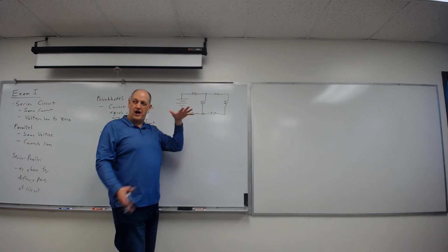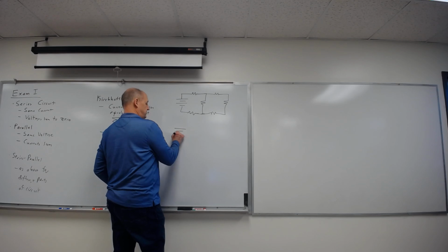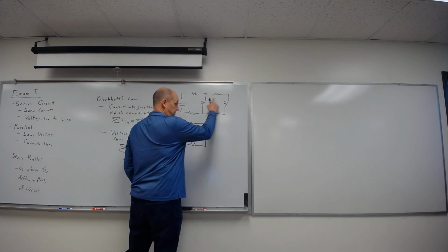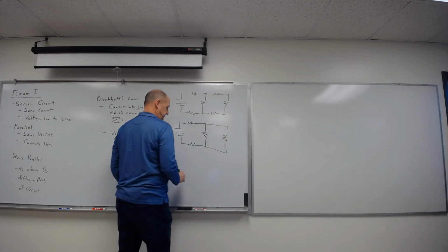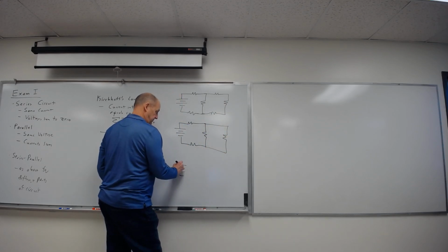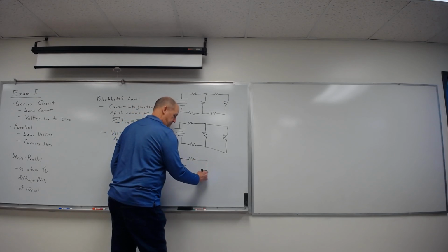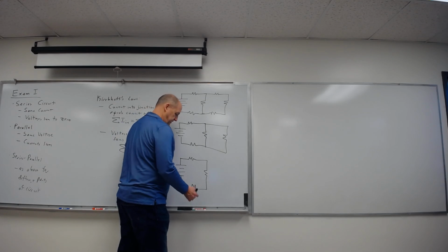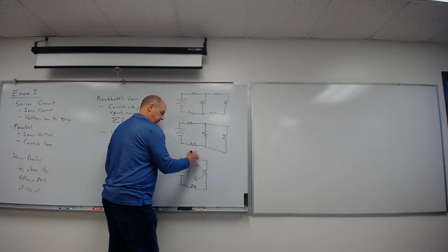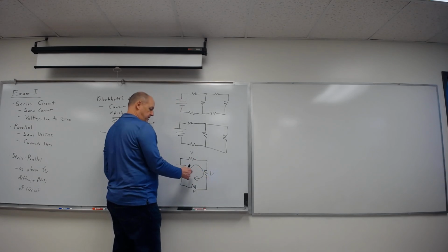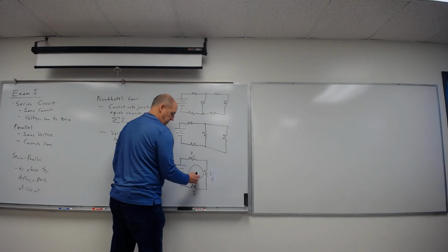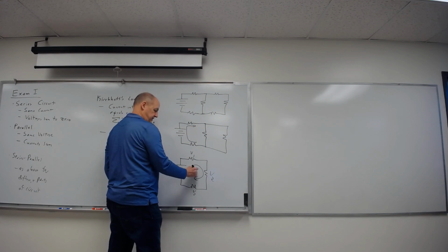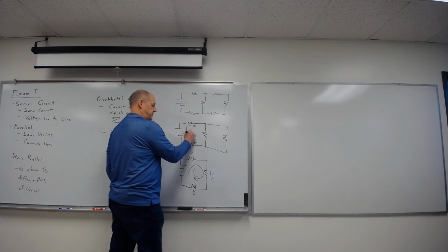And I can go where I'd write all of them out, so I would come through and each step I would write them out. So combine those 3. Combine these 2. I'm left with a series circuit which I can solve. Find that current. Find these voltages. If I go up here, I'll call this V1, 2, and 3. Go up here. This current through this resistor, through here and through here, that's the same current as I found there. Let's call that I1.